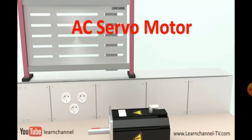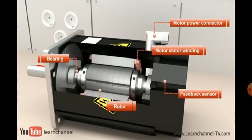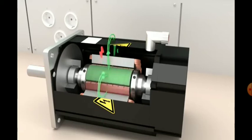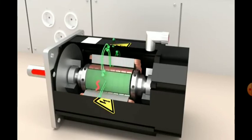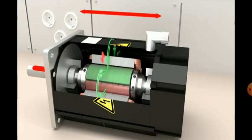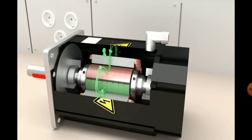Talking about an AC servo motor, you usually mean a 3-phase synchronous motor whose rotor field is excited by permanent magnets, so you get a very powerful and brushless motor of small size. The stator winding produces a rotating magnetic field, whose rotating speed and force is controlled by the amplifier and controller. In order to position quickly, all these motors must have a low moment of inertia, which can be achieved by an elongated shape. The functioning of a synchronous motor was already explained in another video of our Learn channel.